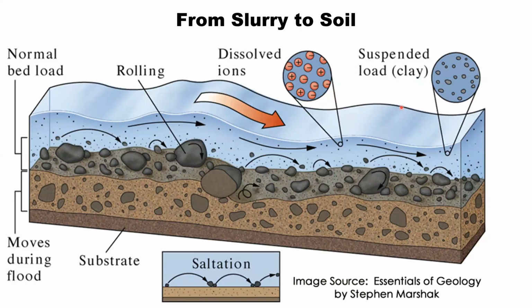If we think about this from a hydrotechnical point of view, we have our substrate here, which is lower levels of tailings that have already been placed, and we have material that is going to move and be eroded as the pipeline is depositing material at a particular point. Then, of course, pipeline spigots may get moved around your facility. You're going to erode the upper layer. So you've got a layer of material that is going to move or be erodible during the next portion of the depositional process.